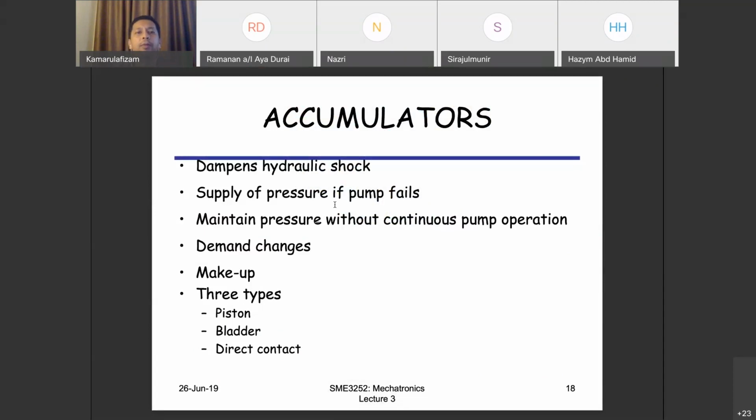Okay, at least kalau belah you punya ada leaking dekat mana-mana dekat actuator, ataupun actuator dia tiba-tiba dia tarik pressure tinggi, so you have accumulator yang akan supply the excess pressure yang your actuator macam perlukan lah, because pump mungkin dia boleh supply pressure up to certain pressure and up to the certain time. Kalau you punya actuator is requesting more and more pressure over the time, mungkin pump tak boleh nak bagi, accumulator yang akan tolong support.